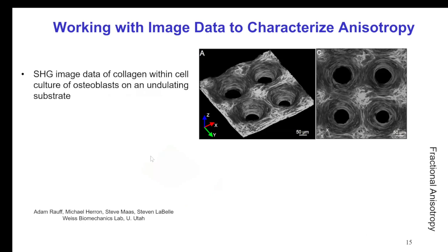Some of the things that we can do with image data, for instance, are assign material properties. Like you might have micro CT data and you want to use that to map Hounsfield number to Young's modulus. So you can do that type of material assignment pipeline now in FEBio Studio.